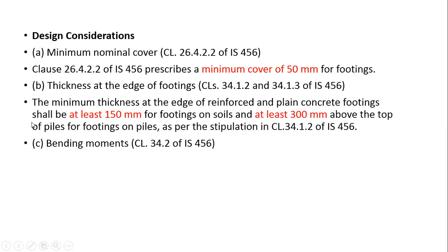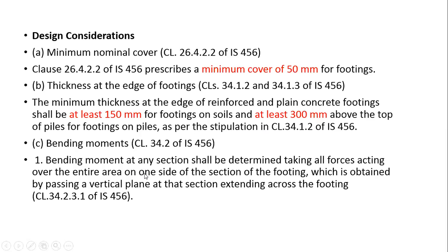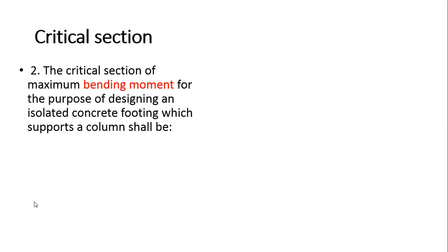Now, next criteria for design is bending moment. Bending moment at any section shall be determined taking all forces acting over the entire area on one side of the section of the footing. I will show you in the next slide how to calculate this bending moment. This is as per clause 34.2.3.1.